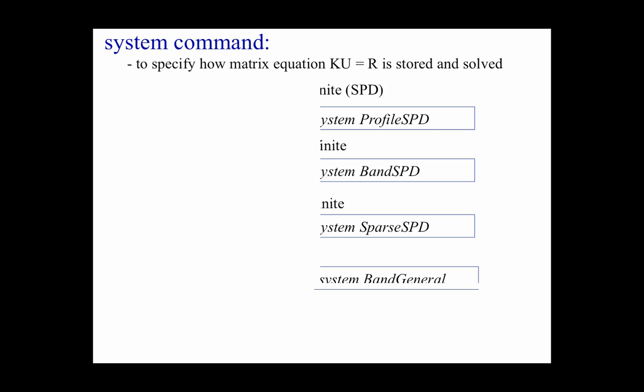So if it doesn't converge, we just try this one? Well, I run the analysis, and if the model's not done in a minute or two, I go, this is taking me too long, and then I start thinking, let me change the solver. So it's basically my patience. That's kind of when I judge it. But as I say, you can go from days to hours just by picking the appropriate solver. So when you've got models that are running for hours, run one time step, then just play with different solvers to find the solver that's going to work best.